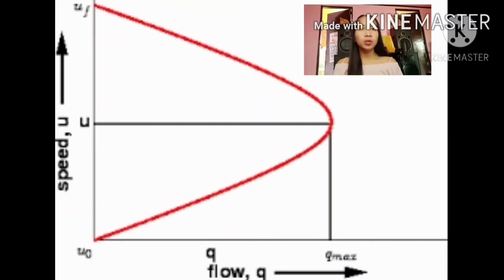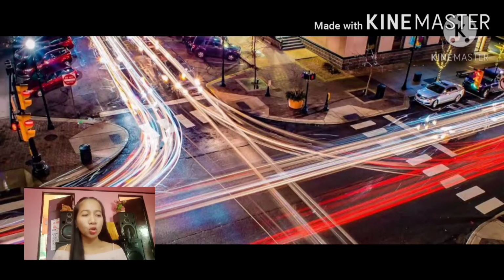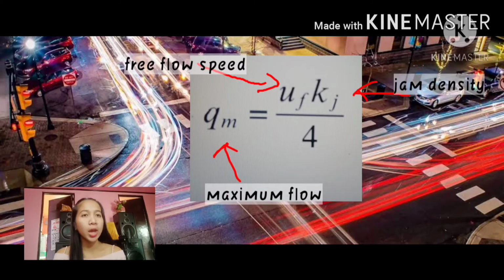For the speed-flow relationship, the relationship between the speed and the flow can be postulated as follows. The flow is 0 either because there are no vehicles or there are too many vehicles so that they cannot move. At maximum flow, the speed will be in between 0 and free flow speed. From derivations, we've come up with this formula: Qm = Uf times Kj over 4.